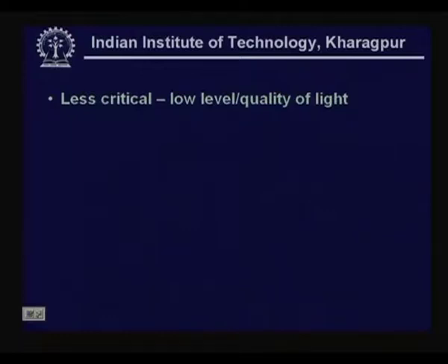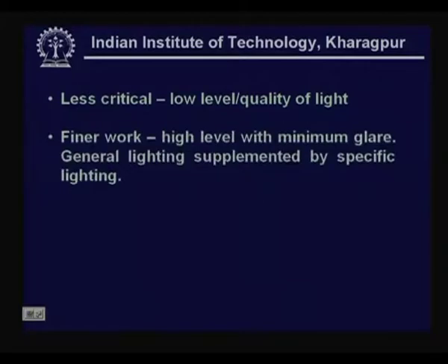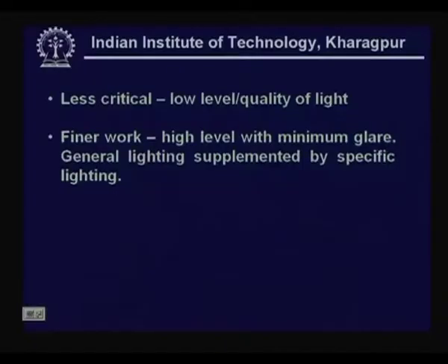Less critical work you can do with a low level, low quality of light, whereas fine work like PCB soldering needs a high level with minimum glare, and invariably in such fine work environments there is supplemental local lighting or specific lighting.